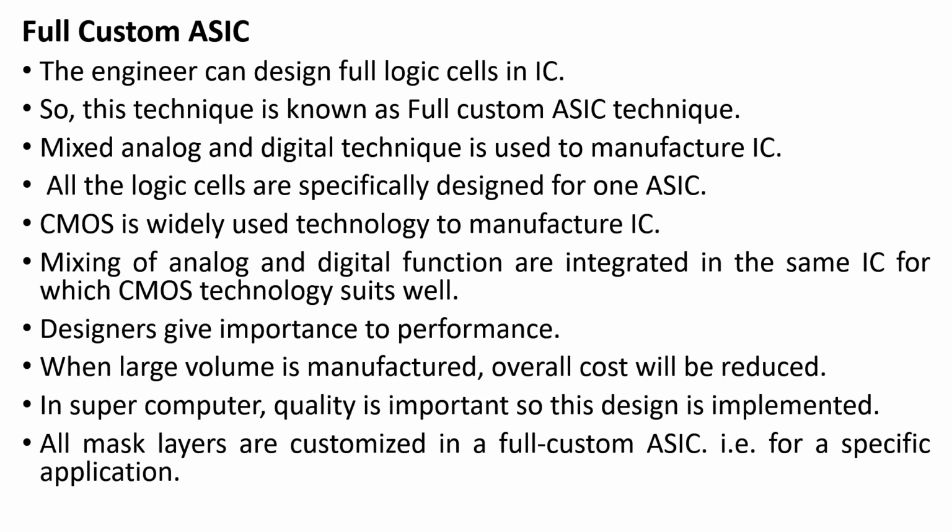Full custom ASIC. Here, the engineer can design the full logic cells in the IC. So, this technique is known as full custom ASIC technique. Mixed analog and digital technique is employed to manufacture this IC. All the logic cells are specifically designed for one particular application. CMOS is widely used technology to manufacture this IC. Mixing of analog and digital functions are integrated in the same IC, for which CMOS technology suits well.